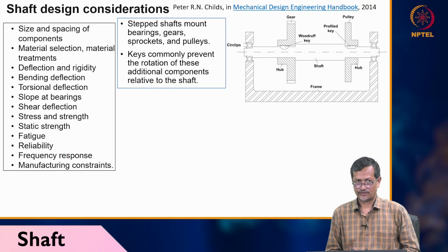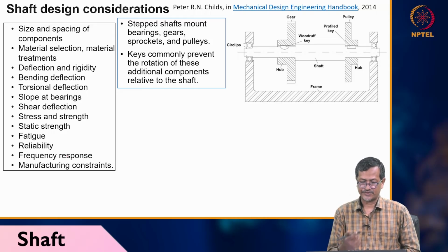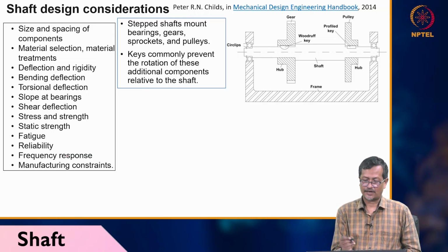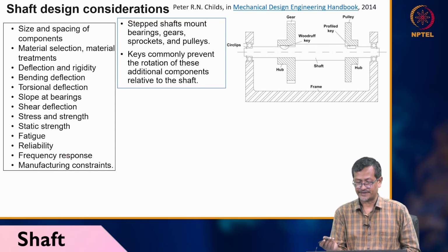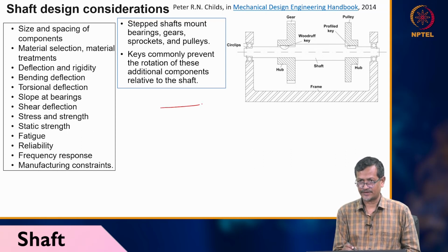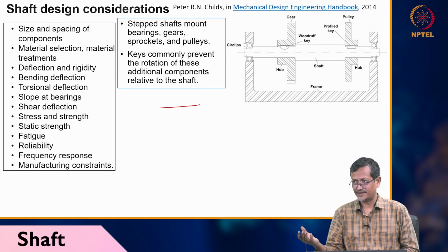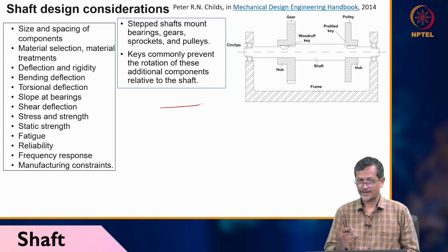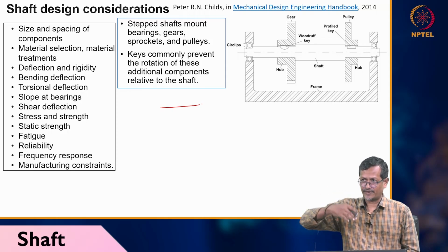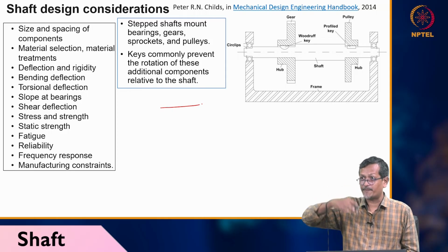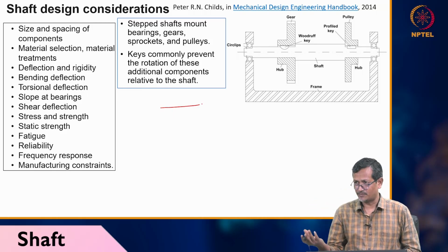Whenever you are buying or designing any shaft, what are the different points you have to remember? You have to check how much space you have and how much power you are transmitting. Let's say you have a very thin diameter shaft and you are transmitting 1 megawatt of power, it's not possible. So first you have to check how much power you are transmitting and what the loading condition is. Loading condition means whether fluctuating load or smooth loading is there. Fluctuating load means, like, a vibrating machine is working, so continuously you are getting alternating force and extra impact force. So then the shaft design criteria will be changing.